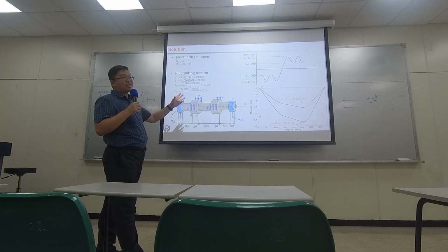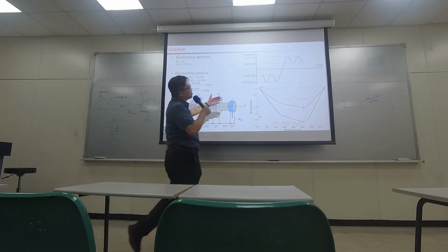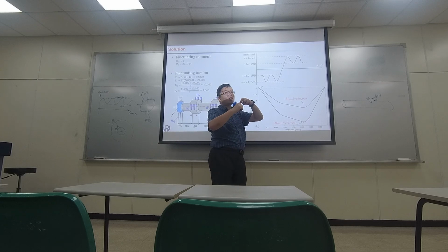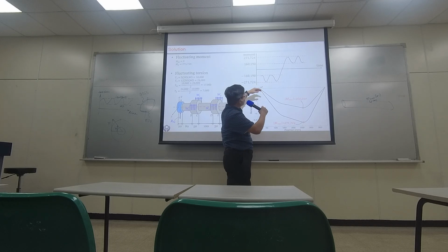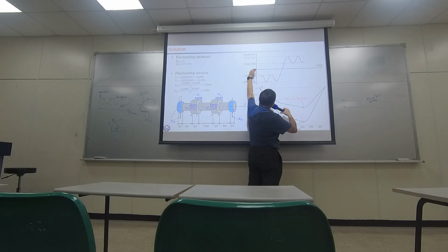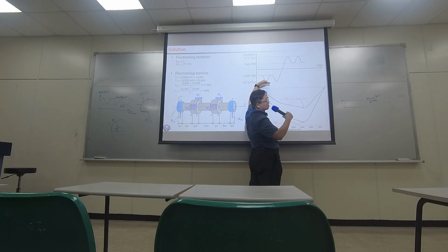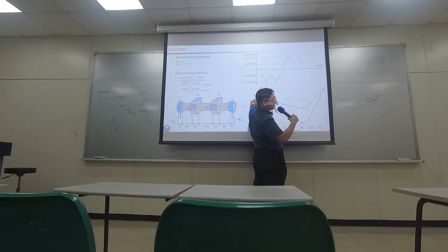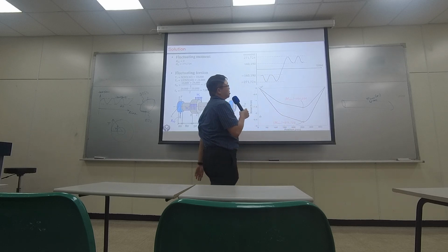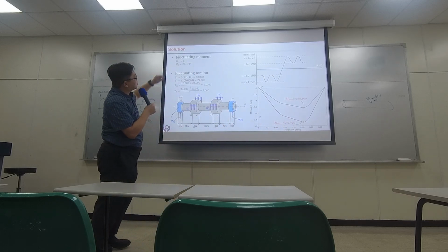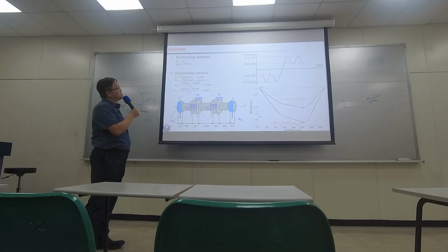So in this case, what do you do? You just treat somewhere inside the shaft as having a mean stress of zero, because you can directly say, okay, it's having a zero mean, but this large amplitude, because that's the worst condition that it could be having as the stress fluctuates. Okay, that's why we can consider something like this.